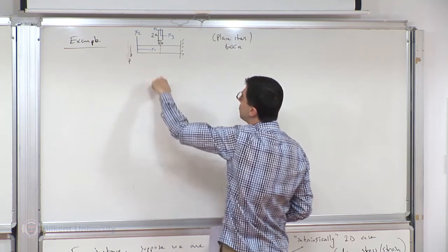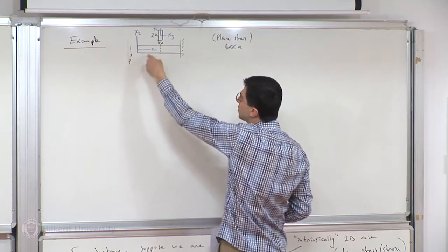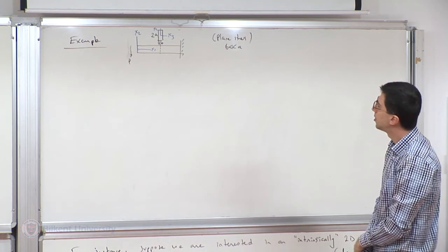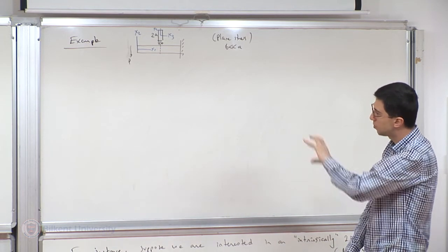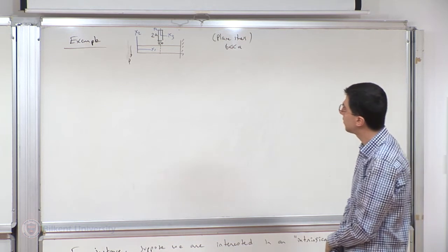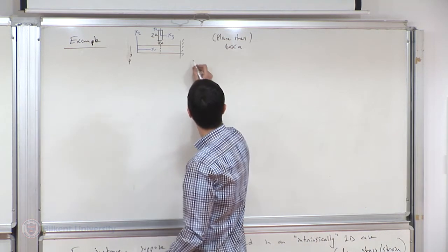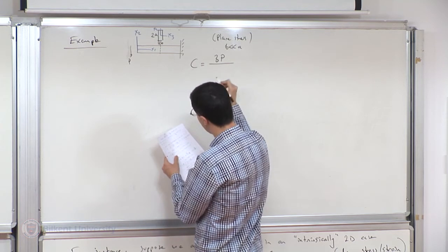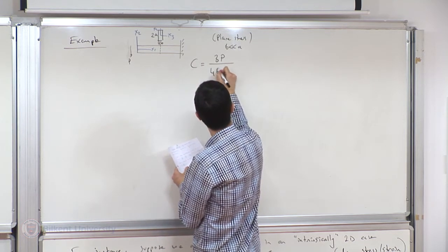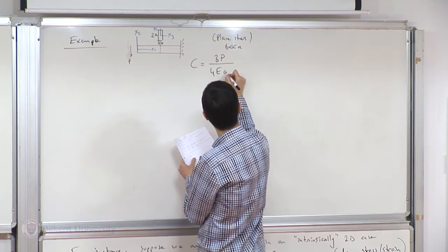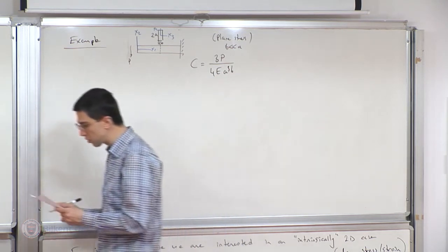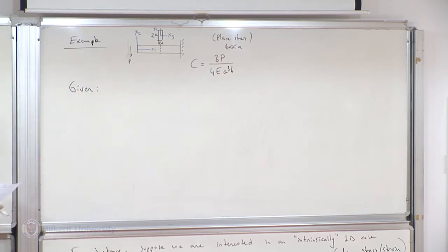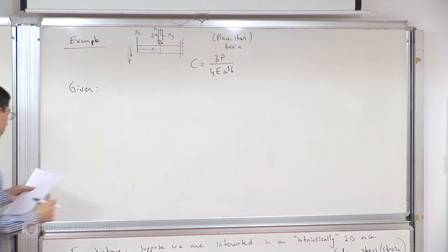So I have a force, and it's going to eventually bend. There will be some internal shear forces, transverse forces, and so I will get a displacement field that represents the deflection of the cantilever bar. Let me define a constant, C. This constant eventually will appear in our solution. So P is the load that we apply, E is the Young's modulus, and A and B are the dimensions of the cross-section. So actually, this is just to sort of motivate you for this strain field.